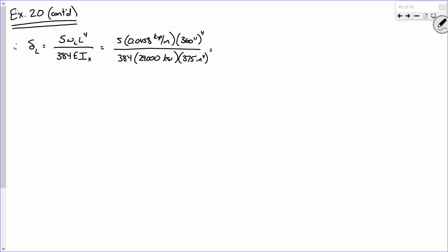Well, let's put it like this. If a steel beam cracks, which it can, it has nothing to do with deflection. It has to do with fatigue. Under repeated loadings, you can develop a crack in the beam. It's kind of like if you take a paper clip and bend it back and forth, what happens to the paper clip right there at that bend? It just sort of gives up, right? Well, that's kind of what happens under fatigue loading. Now, what's the limit? What's the maximum deflection?